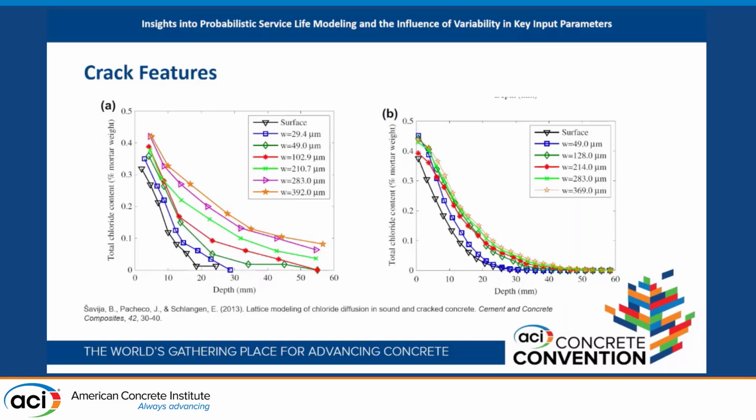You don't see a flat line up to the entire depth of the concrete cover, and then supposedly where it's on crack, it starts diffusing. It just always looks like this. So if it looks like this, it means we can predict this behavior in some way, because it just means that depending on your crack width, your transport is going to be increasing for specific conditions. And the other thing that also is important to note is that even material differences have an effect on this. So the cracks, even though they're important, are not the only parameter that is playing a role in this type of prediction.